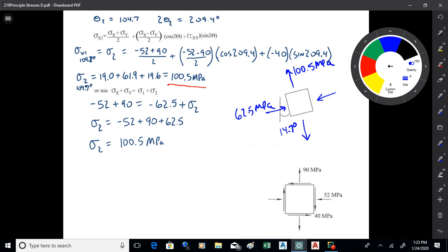And then what's the shear on those planes? Because those are principal planes with maximum and minimum normal stress. You remember that? What's the shear on the maximum normal stress planes? It's 0, yeah. So there's no shear on those planes, okay? Just pure push and pull, pure tension and compression, okay? So, we good with that?